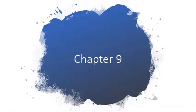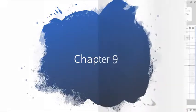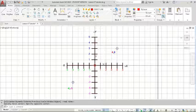The tutorial for Chapter 9 in your Beginning AutoCAD workbook. Our objectives for lesson number 9 are going to be understanding our origin, drawing objects using coordinate input, using absolute and relative coordinates, input using direct distance entry, list information about an object, measure the distance between 2 points, identify a location within your drawing, and create your own master border. The last thing is printing.